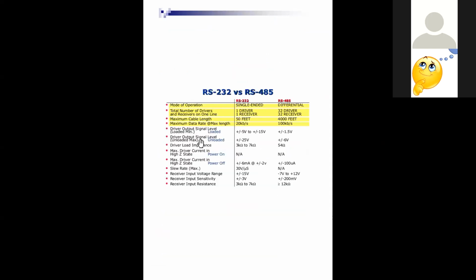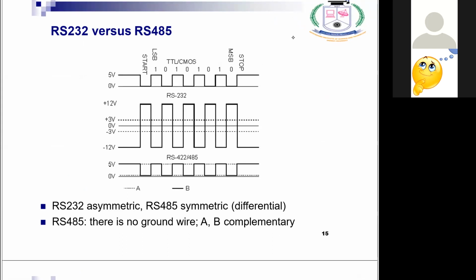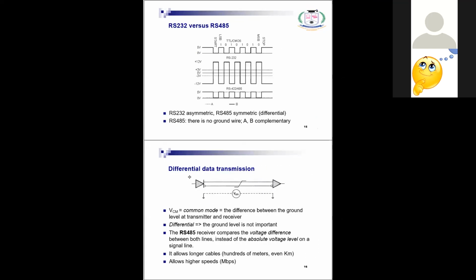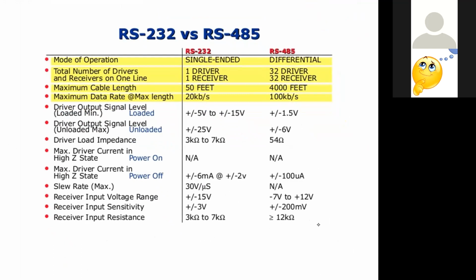Before going on, we will see about RS232 and RS485. Sometimes they will say minus 5 to minus 15, and in some explanations they give minus 12 to minus 3, plus 3 to plus 12. So don't get confused about that. Only the voltage level changes, otherwise it is correct. Are you clear? Negative means logic 1, positive means logic 0, and they fix that. So you have to know the difference. Then we will study RS232 and RS485 in detail.